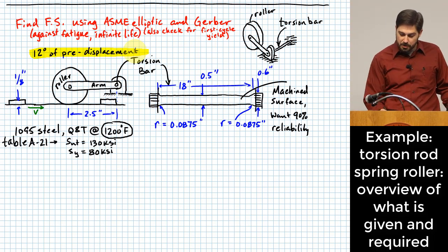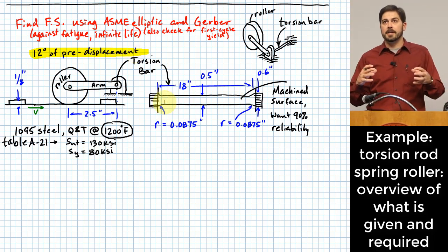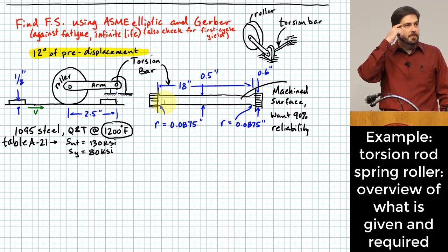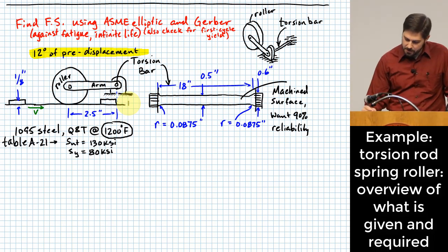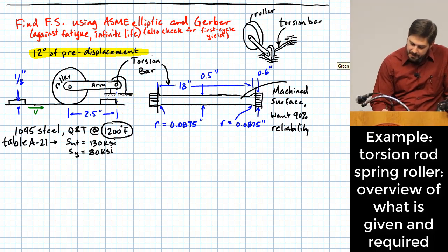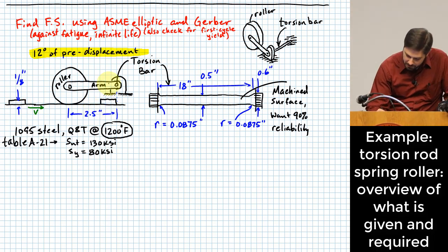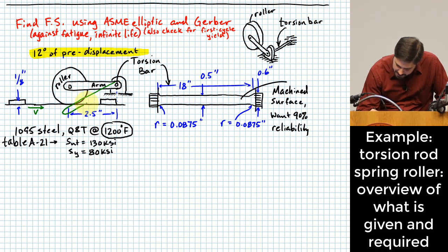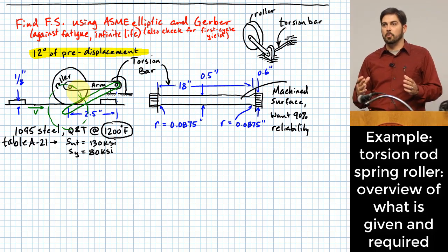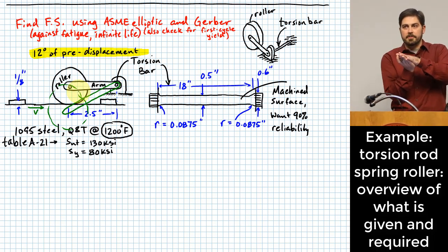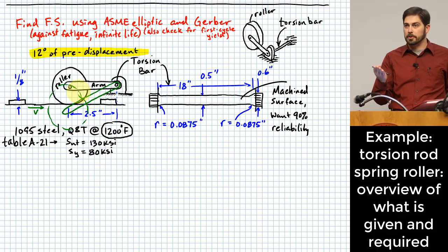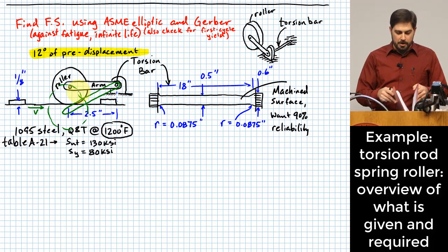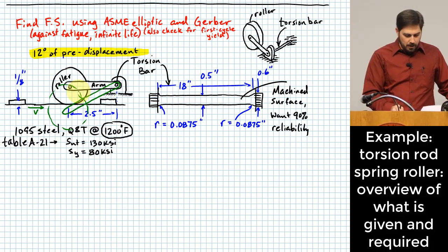And so that's what's going on here, is we're using this torsion bar as a spring to create load that is pushed down from the roller onto these parts as they roll by. So it's already 12 degrees angle. You think about if I was to take the whole conveyor out of the way, what this thing would do is it would spring down to a location 12.5 degrees down from here, and this is where the roller would be if I was to let it go to where it wanted to be. But the conveyor is in place and keeping that from happening, so there's always a load being put on the bottom of this roller, even when it's not rolling over the top of the parts. Okay? All right, so that's going on.